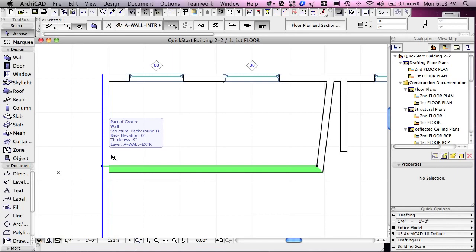The reference line can be top, bottom, inside, outside, but most commonly it's on the outside of a building when you're working on new construction, because that's going to be the critical or defining measurement. On interior walls, it can be on either side, or often it's centered for certain types of commercial construction where tenancy and rental calculations are based on the dividing line or the center line of the wall between tenant spaces.